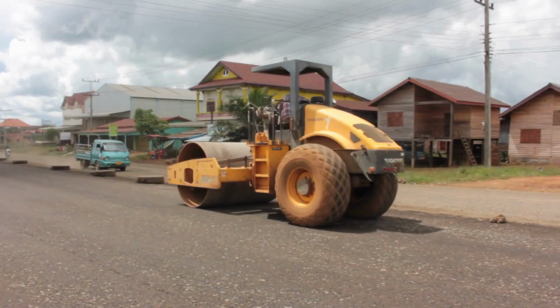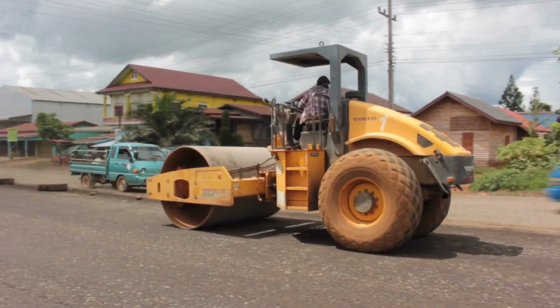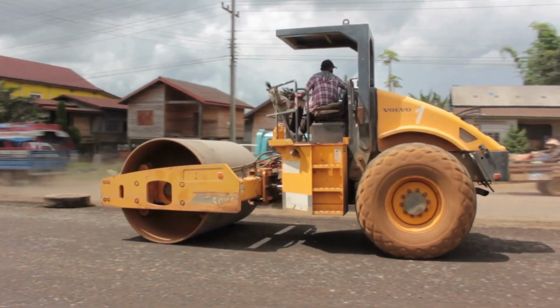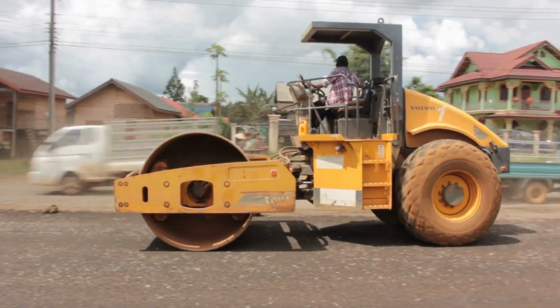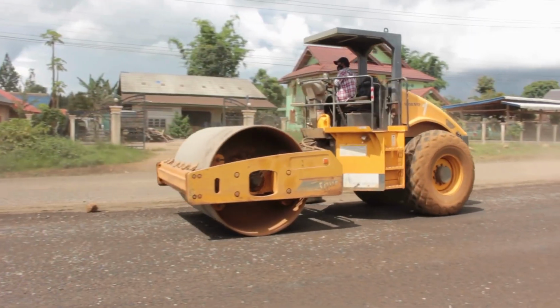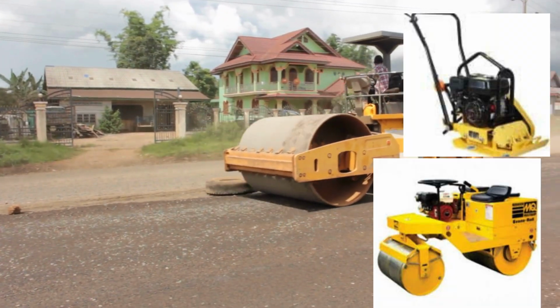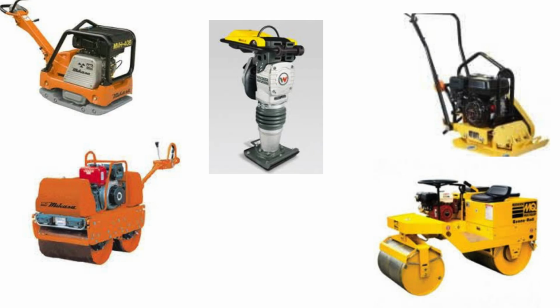At the small scale, the most accessible ground improvement technique is compaction. Just rent a plate compactor before you put in a slab. And drainage, adding gravel sub-base and perforated pipes, and admixture mixing. You can buy lime or Portland cement stabilization mixes for small projects.